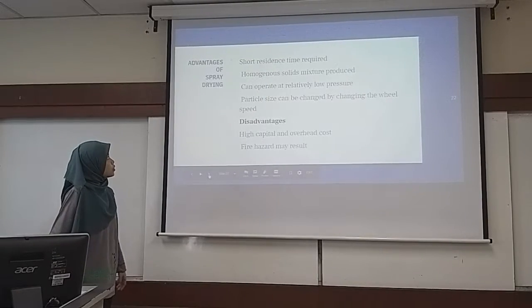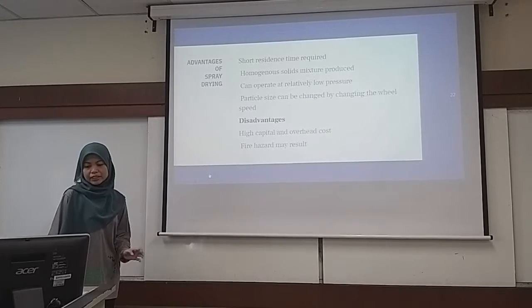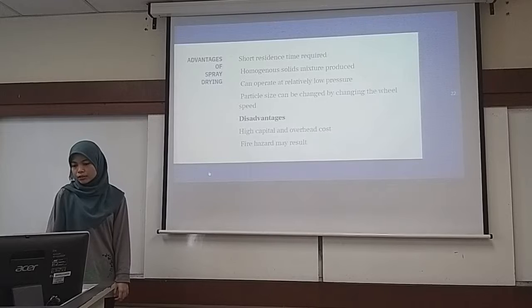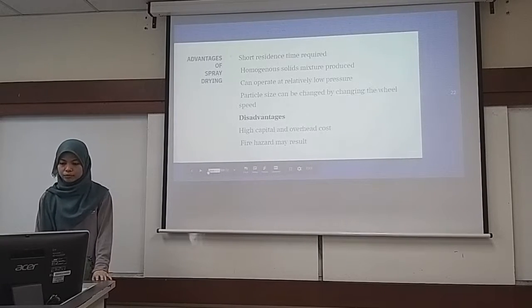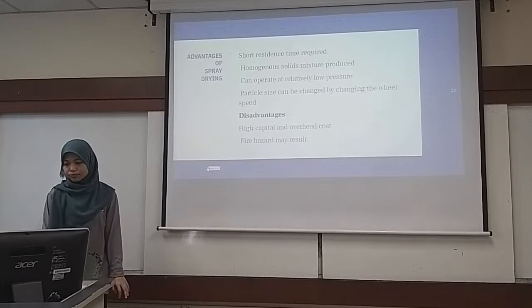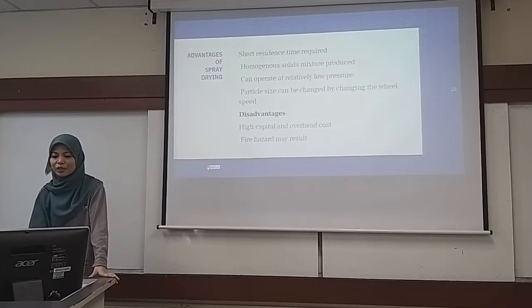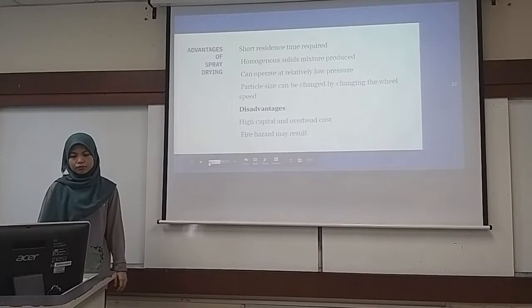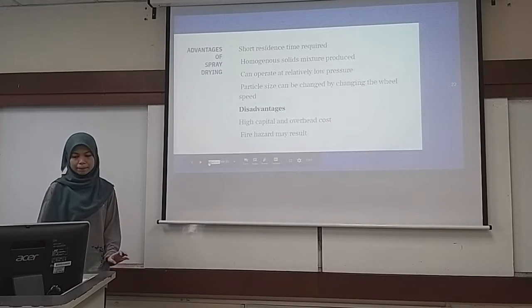The advantage of spray drying, why we choose spray drying, is because it requires a short residence time and produces a homogeneous solid mixture product. It can operate at relatively low pressure. Particle size can be changed by changing the wheel speed. The disadvantages are high capital and overhead cost, and fire hazard may result.